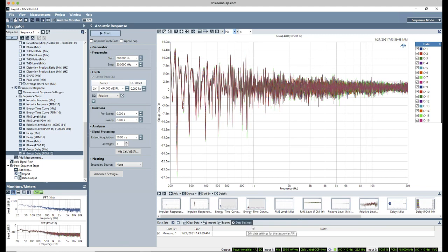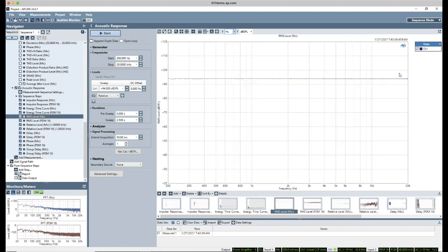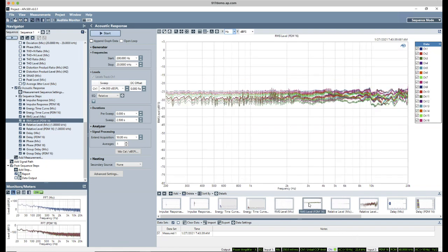Since we have equalized the speaker, so we've got 94 dBSPL across our swept frequencies, to some extent, we can just read the sensitivity right off of one of these graphs. Now, it is biased because there's a microphone that's very close to the speaker and there's a microphone that's relatively far away. So we're seeing some of that effect.